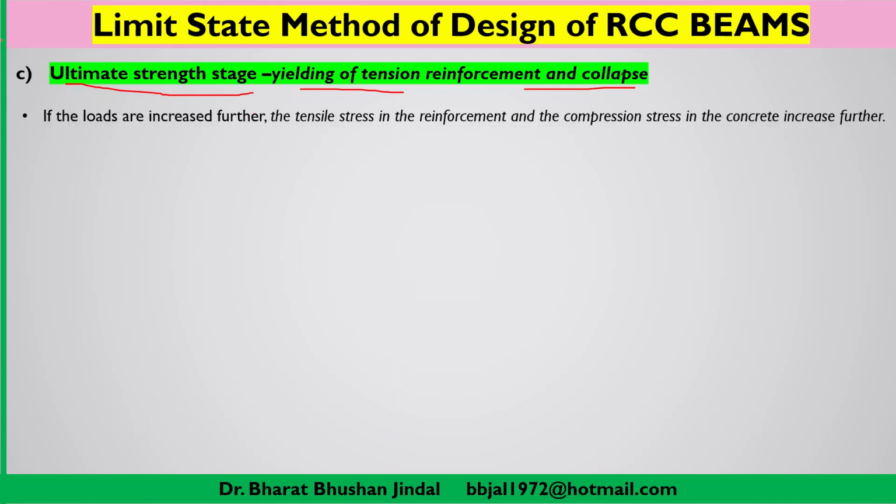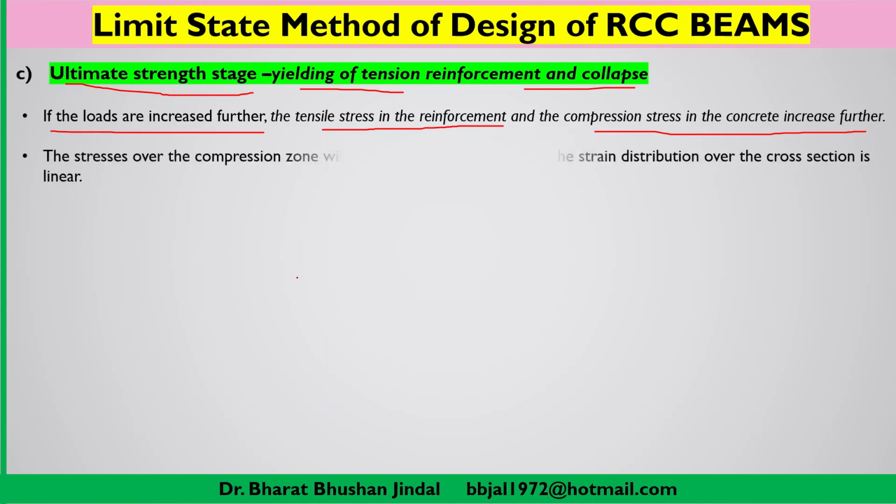Now in continuation of the previous cases where we were increasing the load, if the load is increased further, then tensile stresses in the reinforcement and the compressive stresses in concrete will go on increasing, and the stresses over the compression zone will become non-linear. So now we are moving out of the linear phase. However, the strain distribution over the cross section is linear.